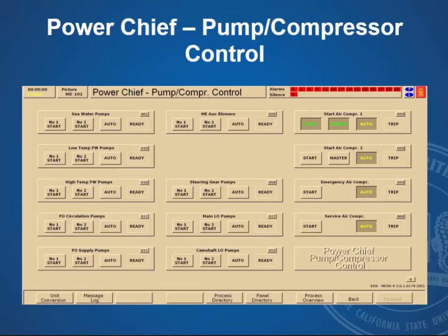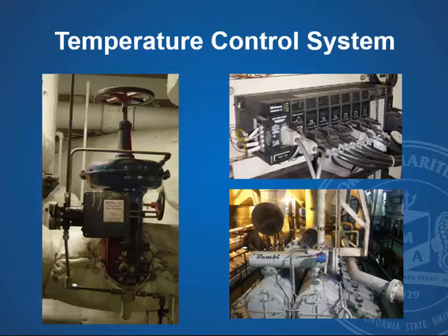As the pressure dropped, it would start and fill the bottle back up and then automatically stop. But in a maneuvering situation, your air usage is very high. Then the master would come on the line and start supplying its full rate, but because you're using so much air, it would drop below that start pressure and the redundant unit would start up. So this is your compressor automation to control the standby status of the pumps and the alarms.